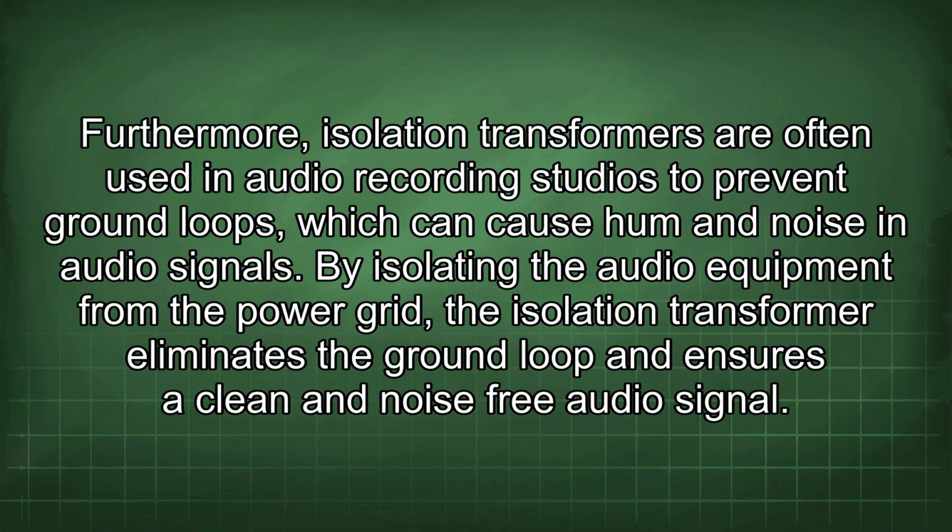Furthermore, isolation transformers are often used in audio recording studios to prevent ground loops, which can cause hum and noise in audio signals. By isolating the audio equipment from the power grid, the isolation transformer eliminates the ground loop and ensures a clean and noise-free audio signal.